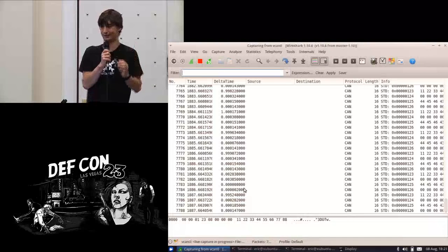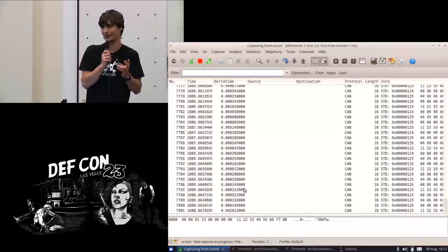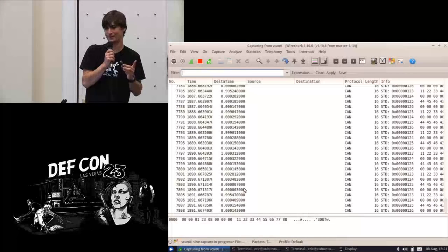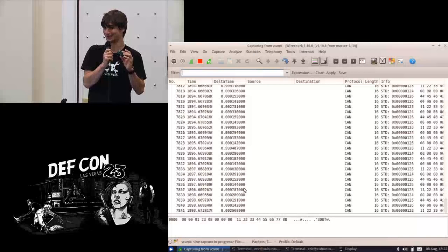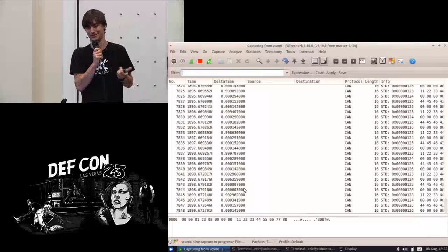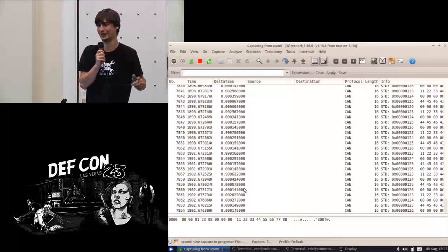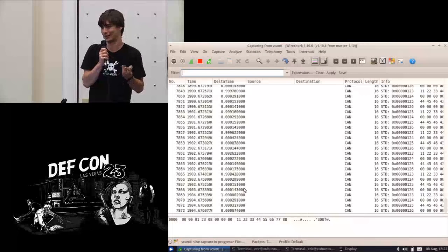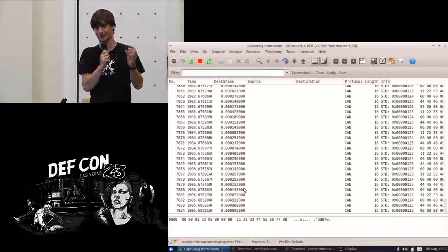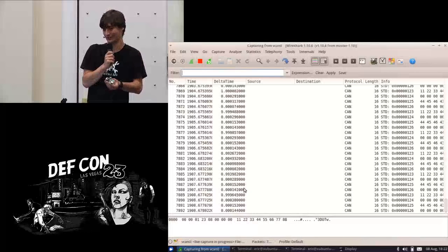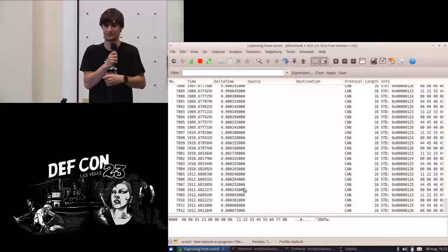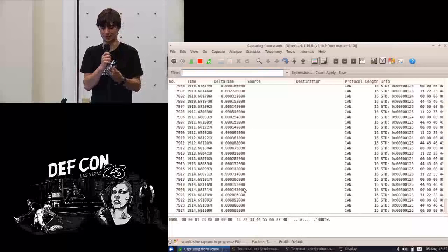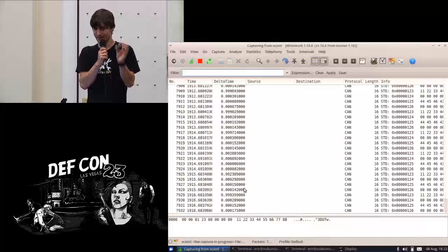The reason being, if you've ever dealt with DB9 cables, they come in two different formats. The really expensive ones come with the right pinout. The cheap ones from China come with the wrong pinout. So this lets you select between both those pinouts. I say the right pinout because it was actually set by CAN Automation 20 years back, and for some reason they don't conform to it. It also has little termination resistors, so if you're just testing two of these or this and one other device, you can terminate the bus. Otherwise, nothing works, so it's useful to be able to jumper select that. And yeah, a DB9 connector on the end.